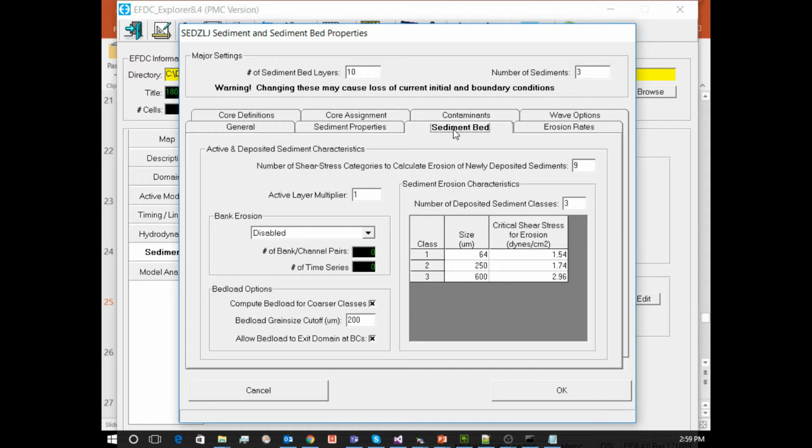And from that velocity field, we calculate the amount of material that was eroding and depositing at the sediment bed. So at the end of that time step, the sediment bed will have dropped if it were eroding. So now the depth in that cell also dropped just a little bit in the pressure solution. So it marches that forward to the next time step.